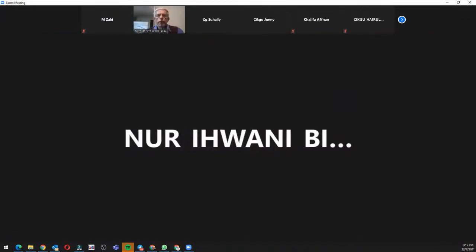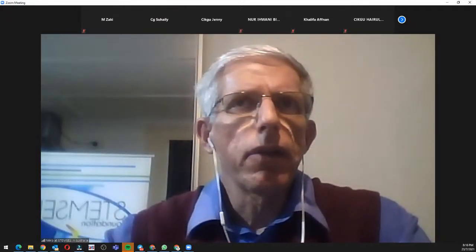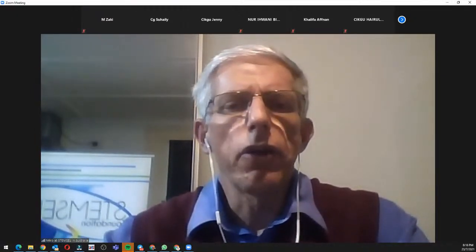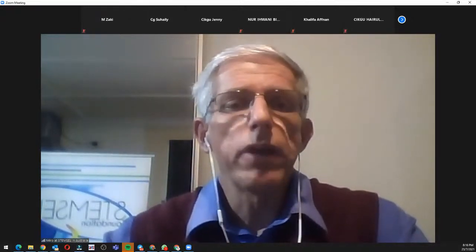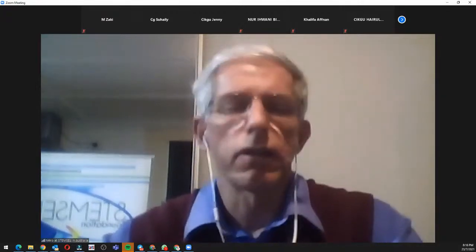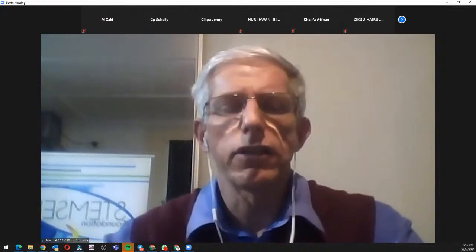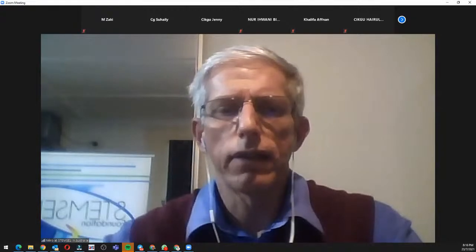Myro, I have a question. Why don't we need to put a timer for the red color? Okay, because there is the green first, and then there is a delay, and then there is the yellow, and then there is a delay, and after that yellow, the red will turn on. And that red will stay on until the repeat function actually happens. So that's why there's no delay after that, because the delay is actually until the repeat starts again with the green. So that is how that works.